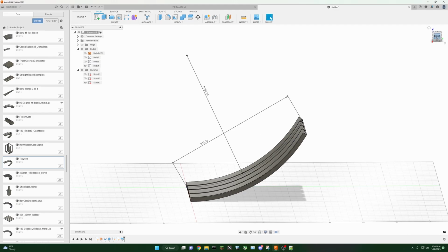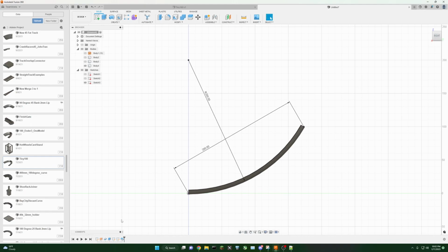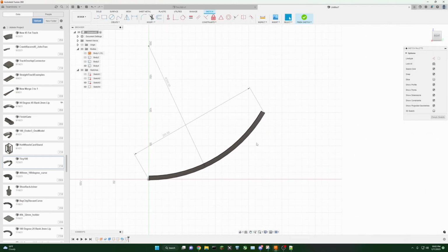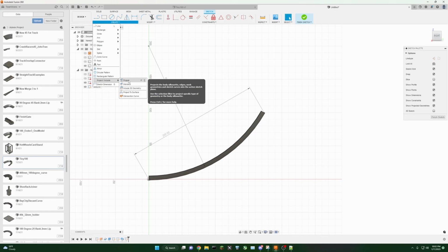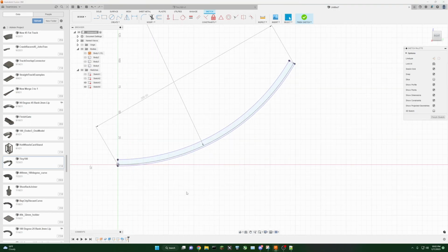Actually, if we wanted to see what that angle is, we can go here after this and create a sketch on the side, and we can project this model. Projecting is taking something and putting it as a 2D representation on our sketch plane. So I'm going to project this body, and I'll show you what that does. Say okay. Now if I hide the body, you can see we have the outline there on the sketch that we're creating.